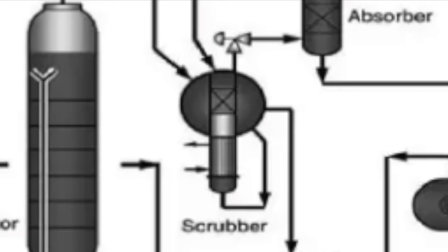As you can see, exhaust gases from the top of the pool condenser are then scrubbed in high and low pressure scrubbers. This is to minimize ammonia emissions. A separate high-pressure ammonia recycling stage is not needed in this process because the concentrations of ammonia and carbon dioxide are low in the stripped urea solution.